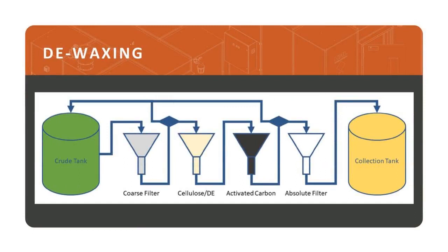All right, so the next process I want to discuss is dewaxing. Dewaxing, as the name alludes, is very similar to winterization. They're achieving the same purpose here. The idea is to remove those lipids from your concentrate. However, dewaxing is different from winterization in that it happens during the initial extraction process, whereas winterization is definitely post-extraction.